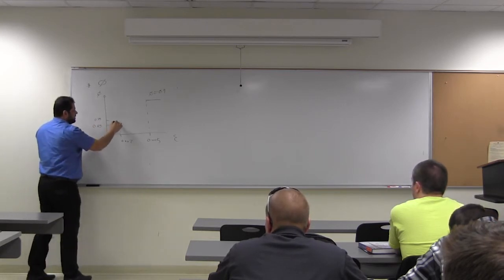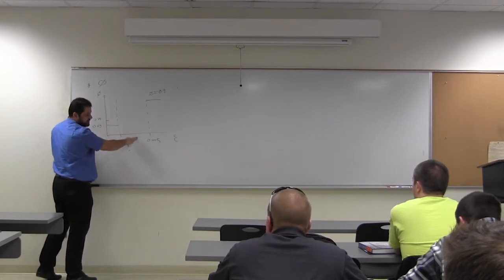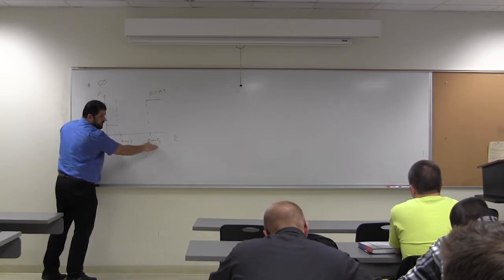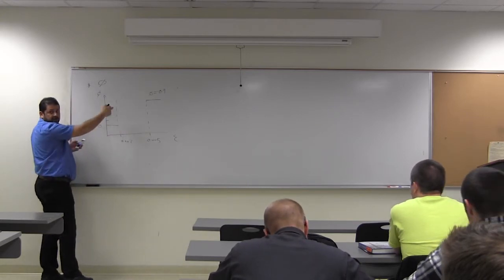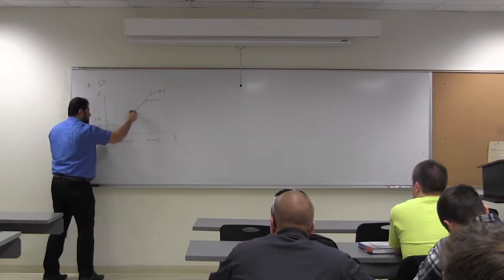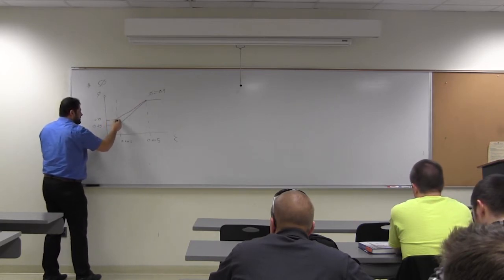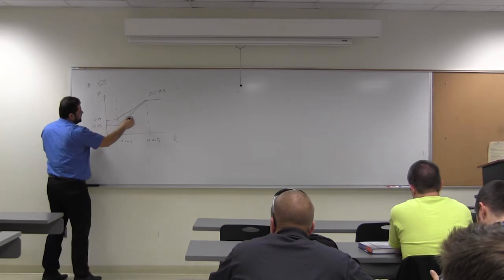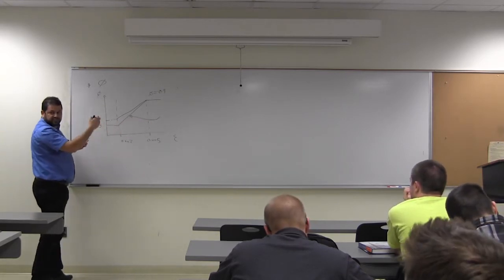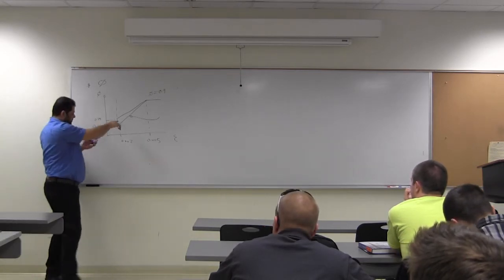Then we said between them there's a transition. If the strain in the tension steel at ultimate is between 0.002, which is the yield strain, and 0.005, the Phi factor is calculated from an equation or linear interpolation, right? You should have this in your handouts. And okay, so what's the equation for this one? If it's in between, once you calculate the actual strain in the steel from the strain distribution, what's this value?